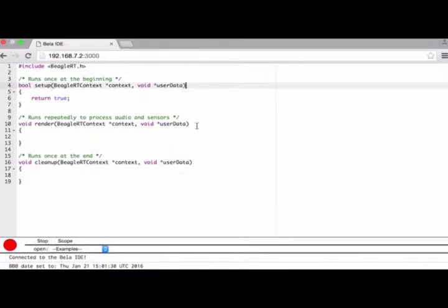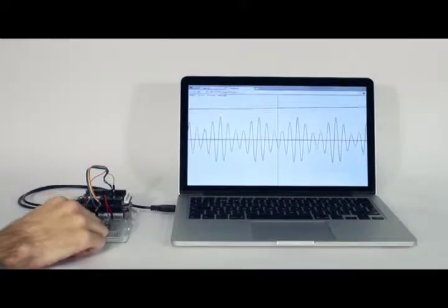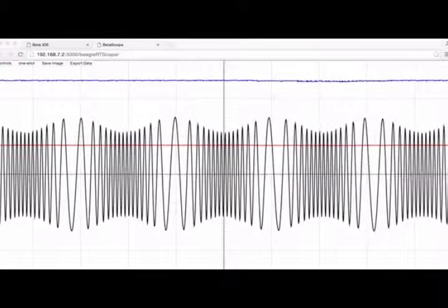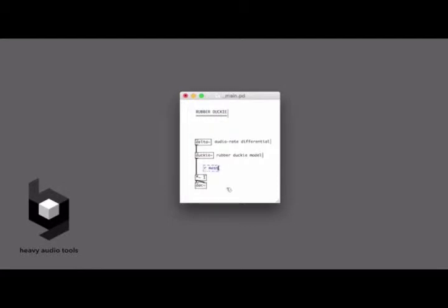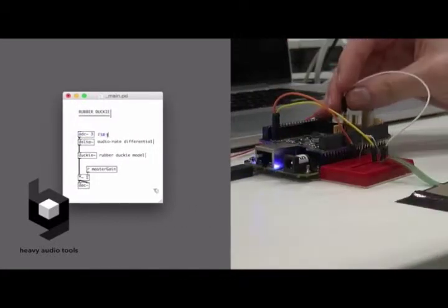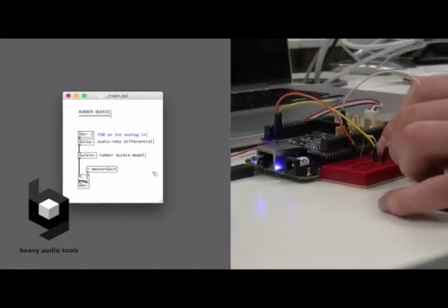You can program it with a lightweight Arduino-like environment using C++. The IDE also has an oscilloscope to visualize your audio and sensor signals. Or instead, compile Pure Data patches straight onto the board using Heavy from Enzien Audio. The generated code is highly optimized and lets you address audio and sensor ins and outs directly from within a patch.